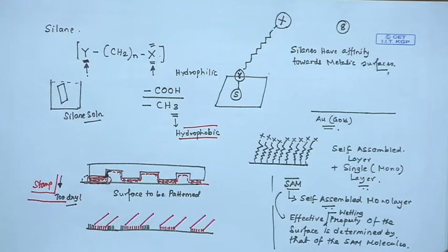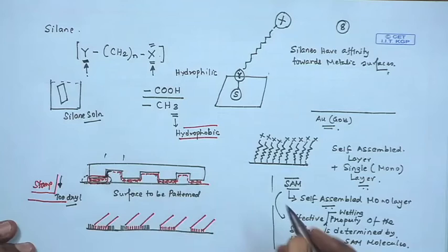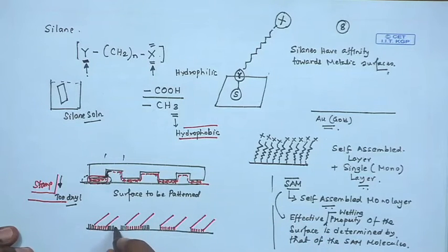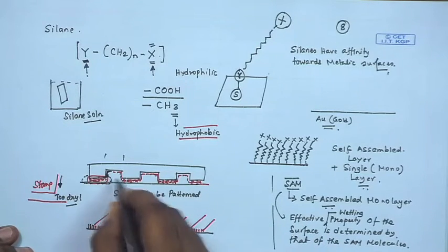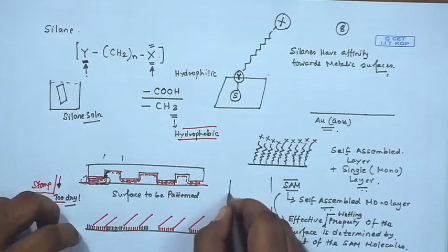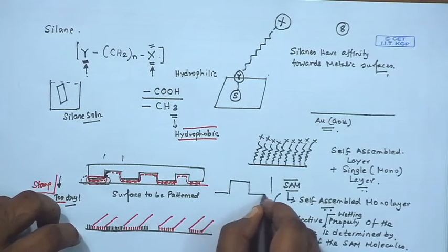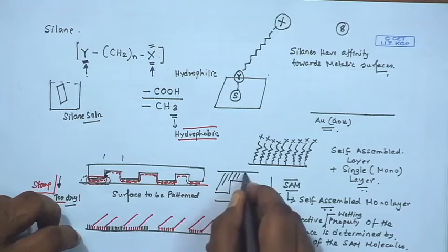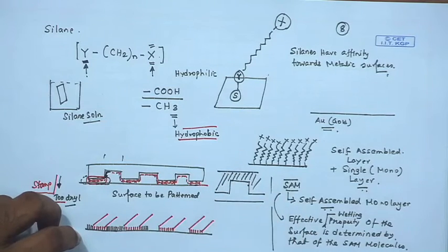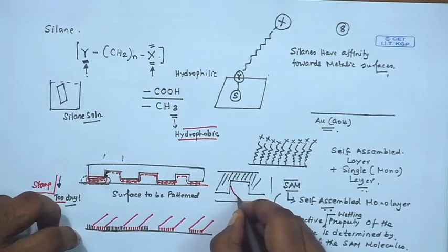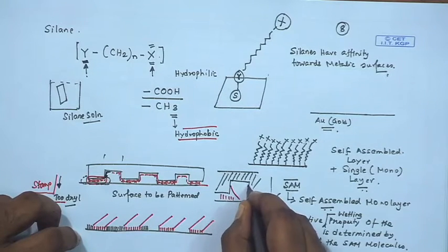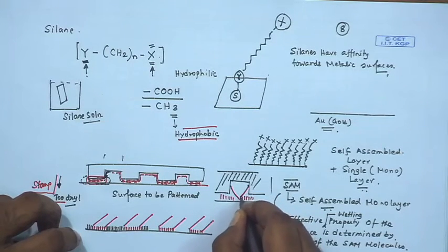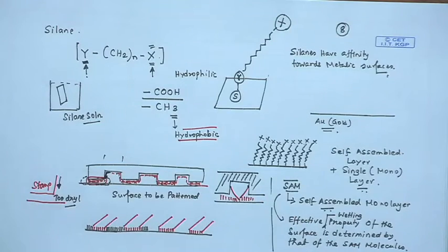And what is the danger of this technique? If there is too much drainage, of course these are small patterns, there is a possibility that the meniscus from two adjacent teeth of the stamp, the molecules are transferring and spreading, this one spreads up to here, they join up and your whole purpose is lost.